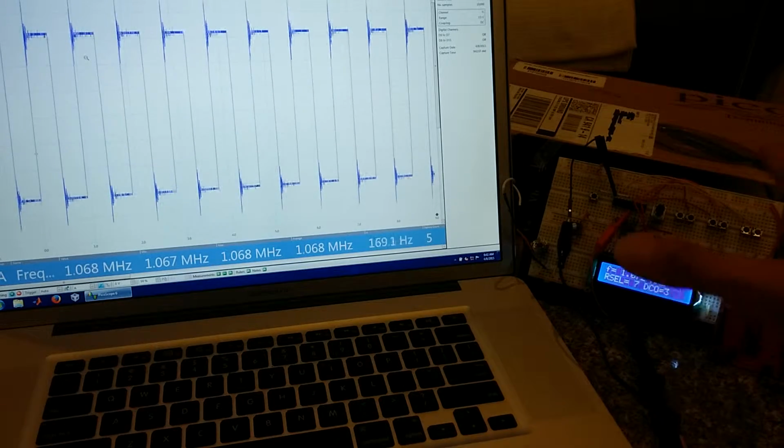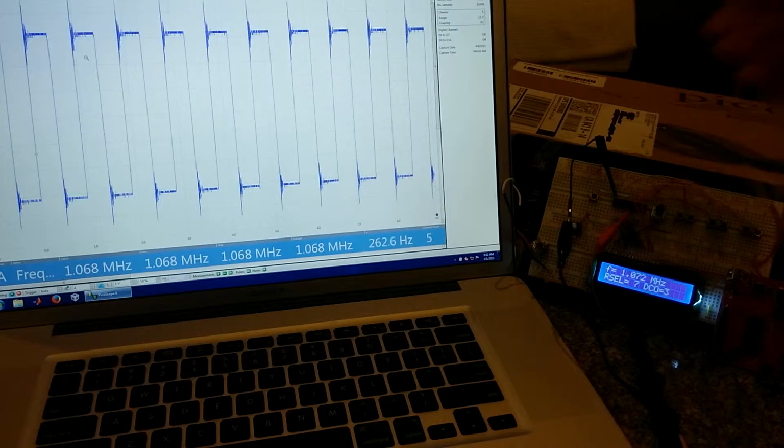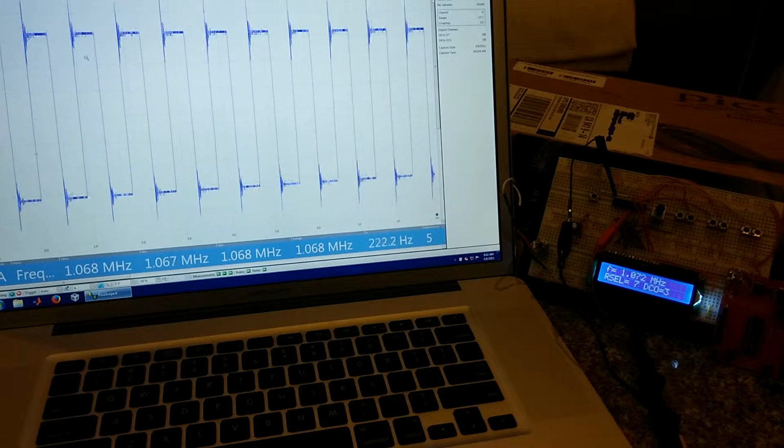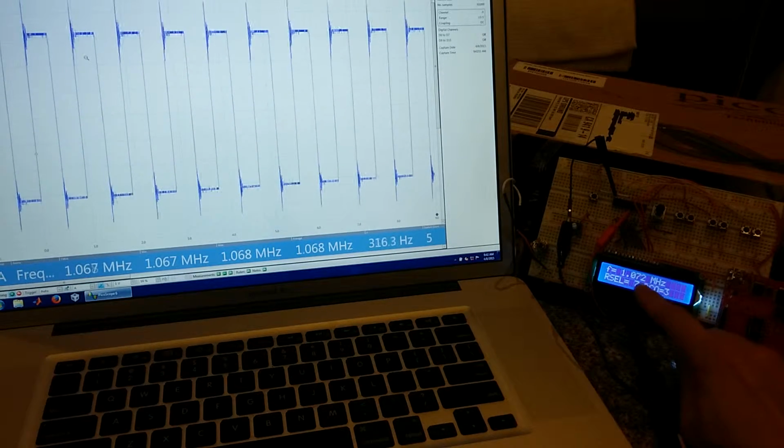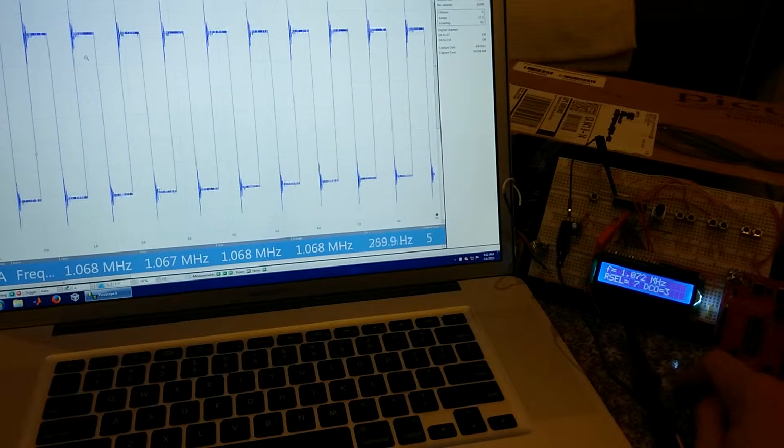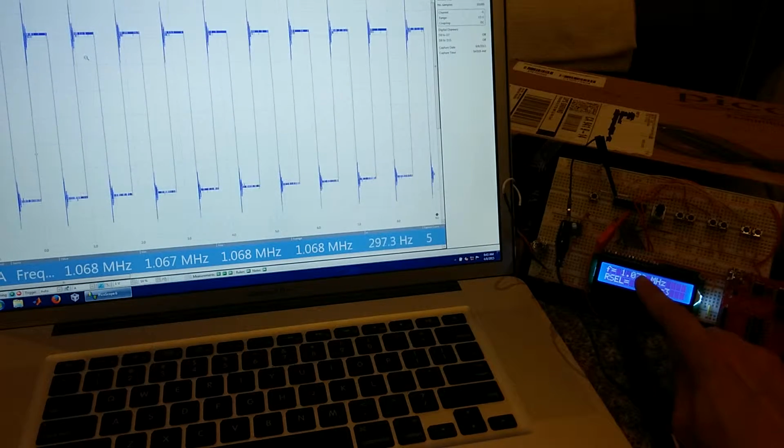What I did was I went through this before and I took all the averages and wrote them down. I put them in the chip and displayed them through the LCD. So I went through all these different values. And what values, you say, John? Well, the R select and the DCO, like I said, these are 2-bit fields in the BCS control registers of the 2553. The R select goes from 0 to 15, and that's the major player in deciding the clock frequency.